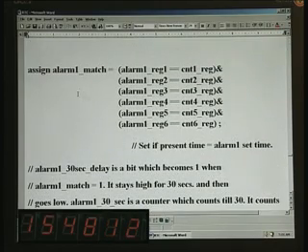And here what we need to do is alarm 1 match, and these are all the conditions. When alarm 1 equals counter 1 and alarm 1 reg 2, these are the hours and the minutes then seconds, when each of them equals the running counter, this is the run time basically, then what you should do, this alarm has found its match, isn't it? You have set one alarm time and a running counter, and when it matches that set value, this is precisely the statement which is responsible for turning on the alarm, right.